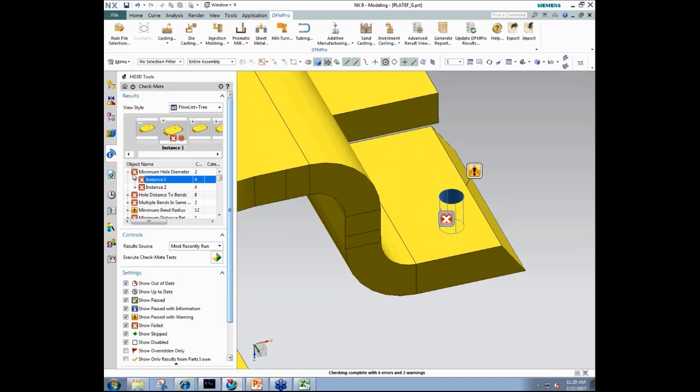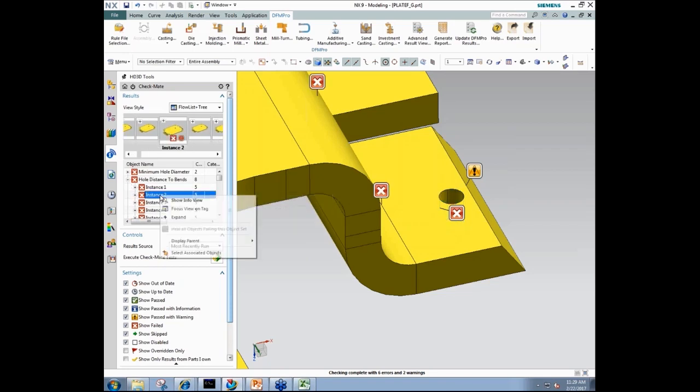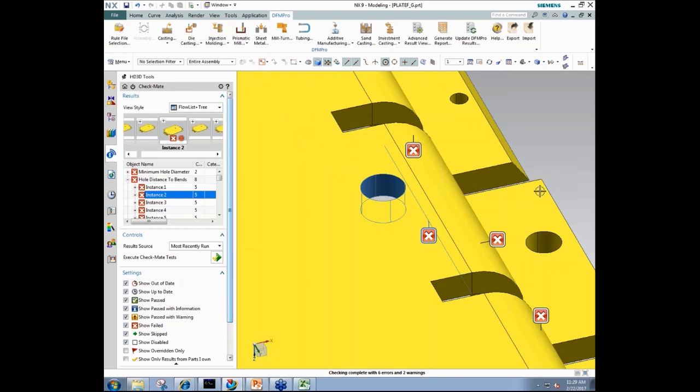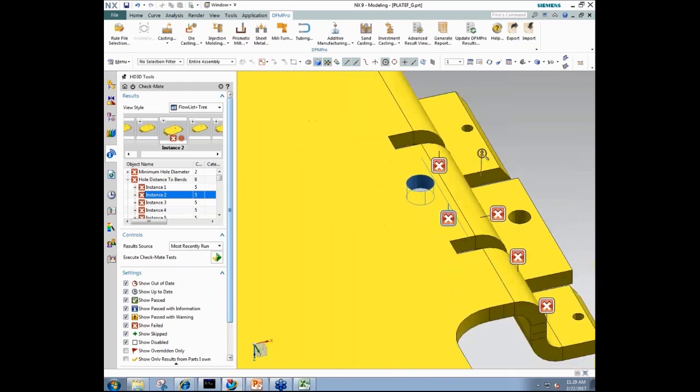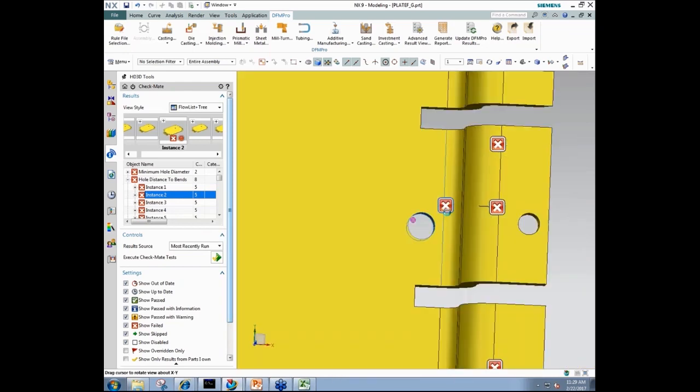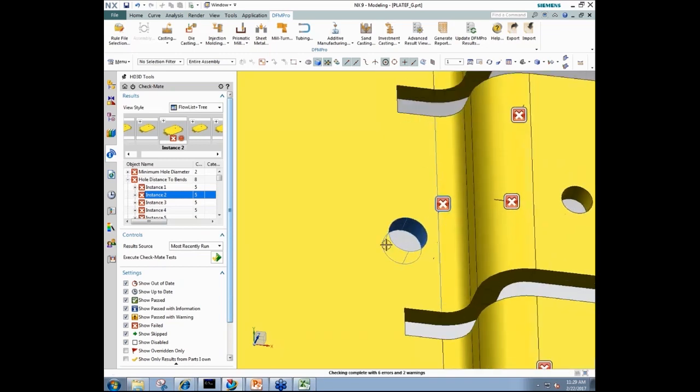So likewise, there could be many more. Some of the things are pretty commonly occurring even in many of these sheet metal parts, like I have got a hole too close to the bend. And this becomes a problem. If I have a hole which has some requirement where there's going to be deformation in that hole, and I have a bend here, the typical process in sheet metal will be that I make this hole either by punch or laser cut or whatever operation you take, and then you will bend it.